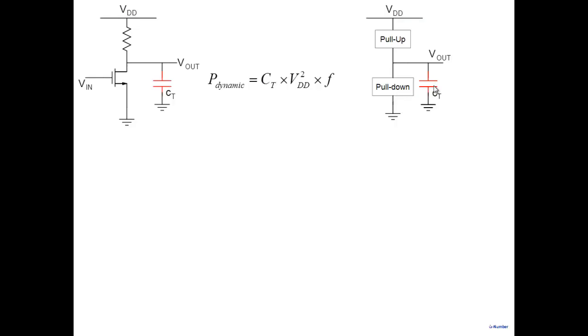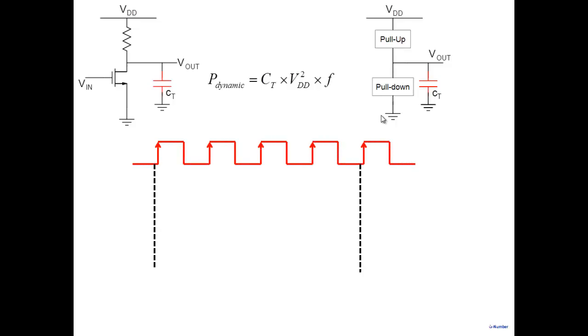And note that of the capacitance that we have put at this particular part here, some capacitance will come from the pull-up and the pull-down device. Some capacitance will come from the next stage itself. So whatever is the source of the capacitance, the power is dissipated in the device which is charging it and the device which is discharging it. It doesn't matter where the capacitance originates from. All right, so that's where the power is dissipated.